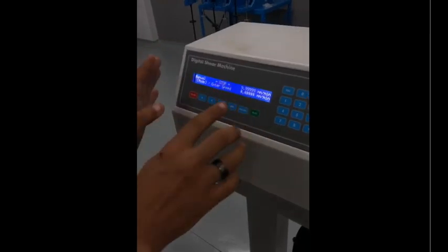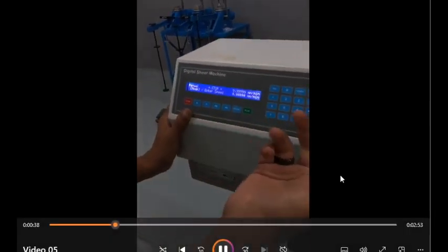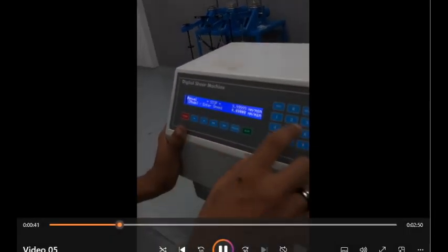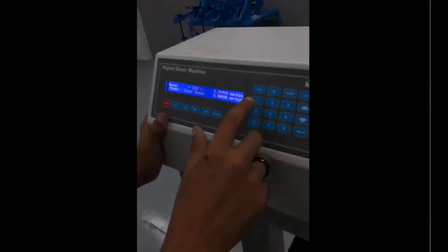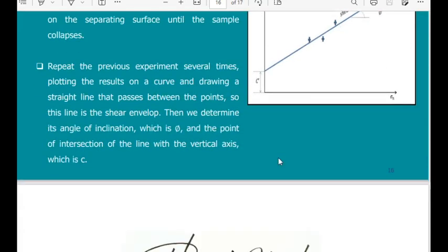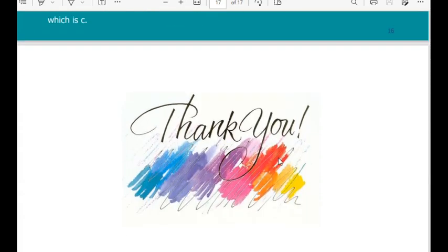These are the loads that we can put on the vertical, these correspond to the vertical stresses that we are going to add to the test. There is a scale for how much we can put, and this load is multiplied by a factor. You will know this when you go to the lab. Then you start the test and you monitor everything on your screen. This is enough for the time being.